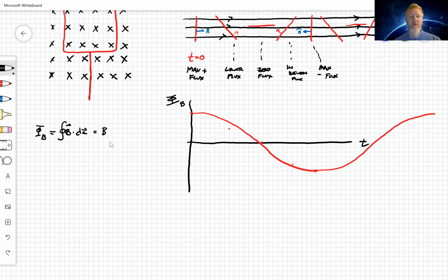But now it's the integral of the dot product of n hat with dA, which is going to force a cosine in here, right? So I'm going to get the area of the loop, but then I'm going to get the cosine of the angle in there from the dot product. And if it's rotating, then that becomes something like an omega times a delta t for the interval, right? So that's like a displaced angle.